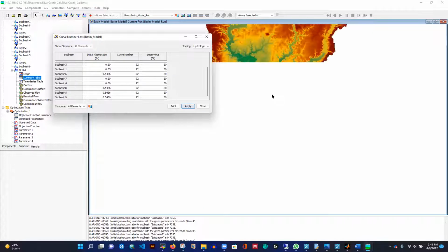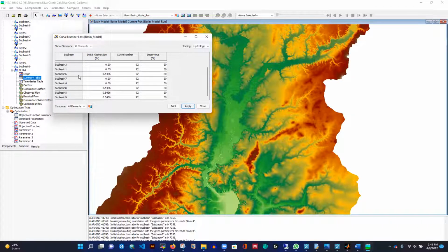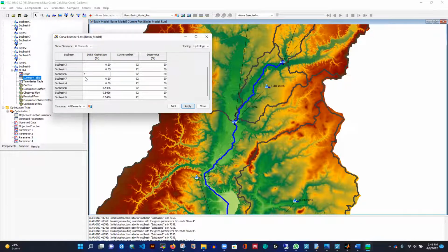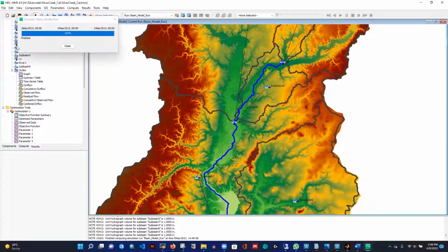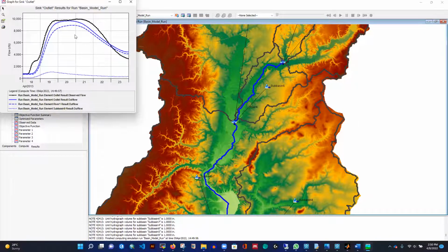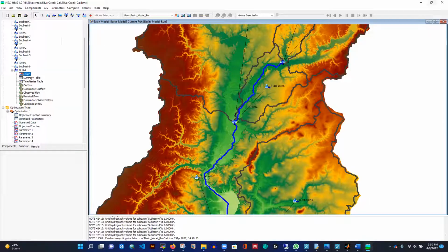And then we can reduce the values for this one, 3, this one 6, right? What is the value of subbasin? It's subbasin number 6, so we can do this to subbasin number 3. Oh, we have to reduce this one to 0.30 so that we can get some improvement there. Okay, so save the model. Definitely it will improve this time a little bit, I guess. Yeah, it's touching, I guess, right? It's close enough to touch that. And then we have even 923.